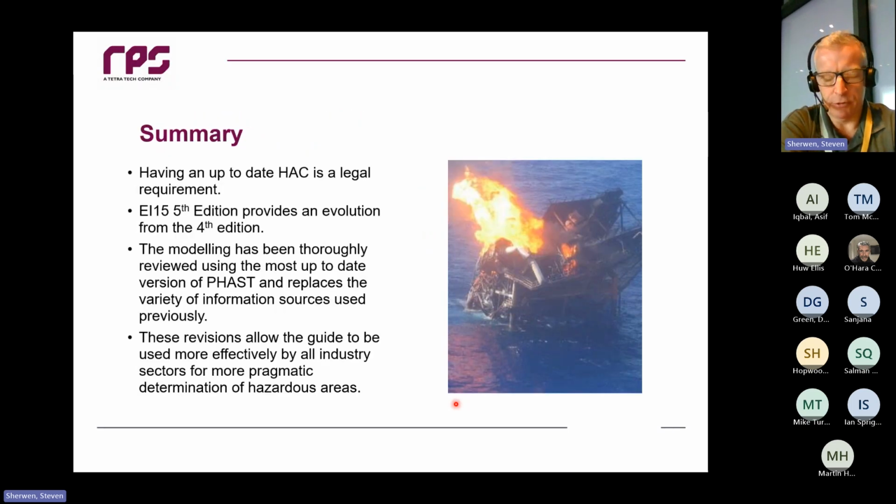Okay, so just to close out before I hand back over to Dave, as you all know, having an area classification is a legal requirement under DSEAR, and we feel, well, so I say we, the Energy Institute feel that this version is, if you've got hydrocarbon systems, a good document to use, and the change from the 4th edition to the 5th edition keeps this document relevant, especially with the introduction of hydrogen as a fluid category.